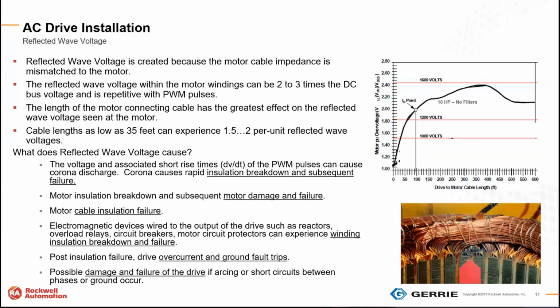The other thing we've seen as well is if they're on really old motors that did have a very high phase-to-phase insulation rating, they start to actually arc, and the arcing will cause failure of the drive. So the reflected wave punched through the insulation and caused some arcing within the motor itself, and that arcing ended up damaging the IGBTs within the drive, excuse me.